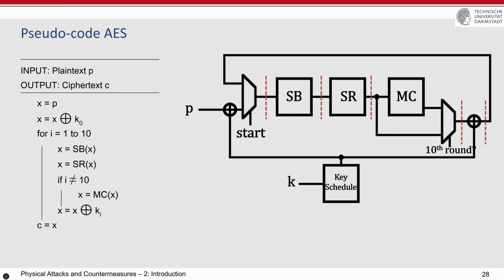Then what happens? More clock cycles are required per AES round, but the clock can be faster. And at the same time, if you build a pipeline, then you can give multiple plain texts one after another. If you have 1, 2, 3, 4, and 5 register stages, then you can give 5 plain texts consecutively to this. And when the ciphertext is generated, then 5 ciphertexts are also generated consecutively after each other.